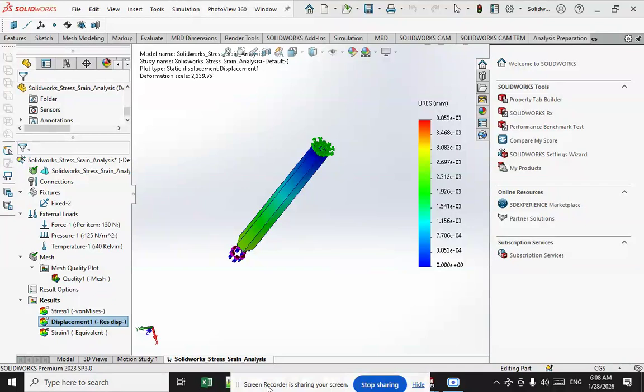In engineering applications, such members experience small deformations, and the reduction in cross-sectional area is very small and can be neglected. For example, the cross-sectional area is assumed constant during deformation. For this case, the stress is called engineering stress or nominal stress and is calculated using the original cross-section, which is sigma_e equal to P divided by A0, where P is the applied load and A0 is the original cross-sectional area.